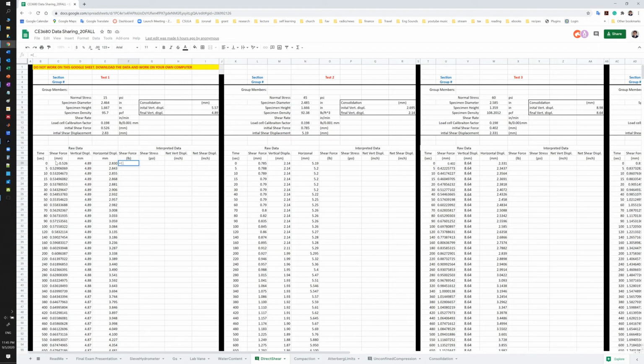So you want to have some initial readings to record the data, but after that, when you do the interpretations, you just need to correct for it. So now we do the data corrections. The very first step is you take the readings and subtract the initial values, and you want to anchor it. That gives you an offset, so you go back to 0.